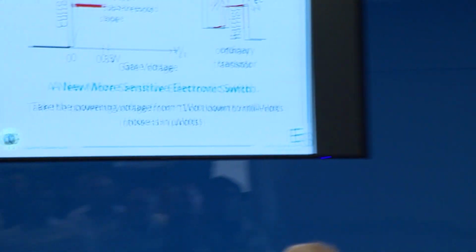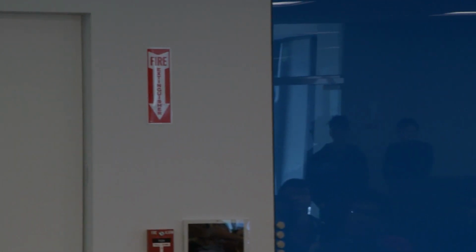The reason is that most of the time the transistor is doing nothing. It's just waiting. For example, on a keyboard, let's say there is a transistor connected to the Q letter. Well, you don't use Q very often. So the transistor is sitting around a lot. And when you turn it off, you don't want it to be leaking current while it's waiting. And so you end up with your Boltzmann factor, you need at least about 0.3 of a volt just to deal with the Boltzmann factor.